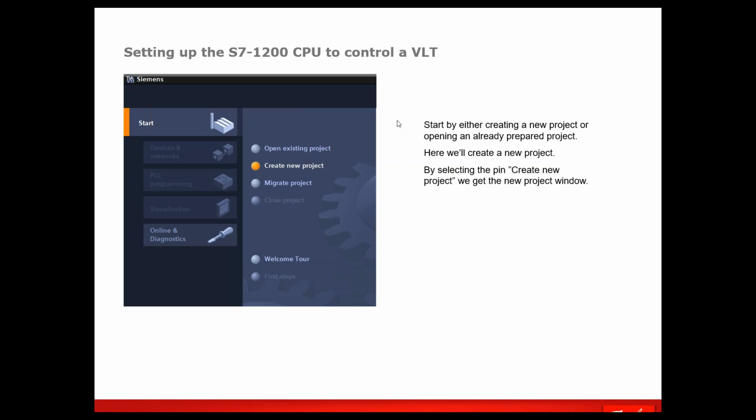So to start configuring the PLC, you would open your TIA Portal. In this example, I'm using version 11. I think now, I forget if they're 15, 16, or 17. But again, when we talk about the GSD or function blocks, they get compiled into the project and updated and go with the project.